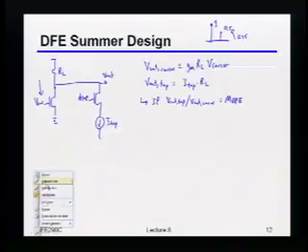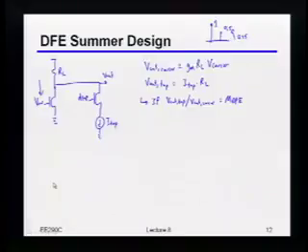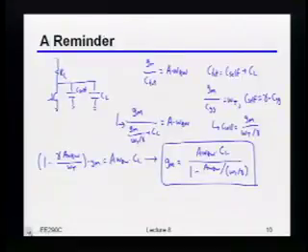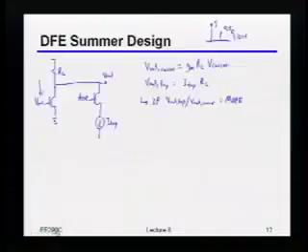So we're trying to calculate what that approximate loading cap will be? So just like 2 slides ago we calculated what the GM needs to be as a function of where you're operating relative to the gain bandwidth, what I'm going to do now is, as a function of this MDFE, calculate what the GM actually has to be. And in fact, I'll recast it so that it'll be more directly in terms of the bit rate you're operating at, what the digital delay is, and things like that. You'll see it'll be slightly complicated, but it'll be like a one-line expression.